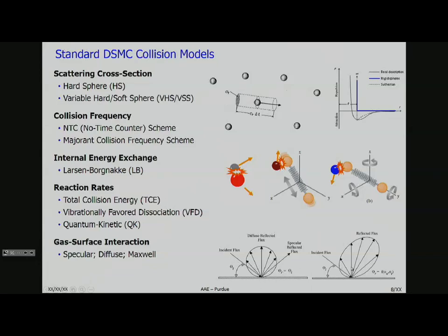The real way is a bit of an average between them. That's not realistic, because naturally you have to account for things like surface roughness. No surface is completely smooth on the atomic level, so it won't just be a perfect mirror-like collision. I believe most surfaces are about 90% diffuse, 10% specular. That's a solid assumption in most cases, certainly for the cases you might be running for your project. And in SPARTA or any DSMC solver, it's pretty easy to specify.